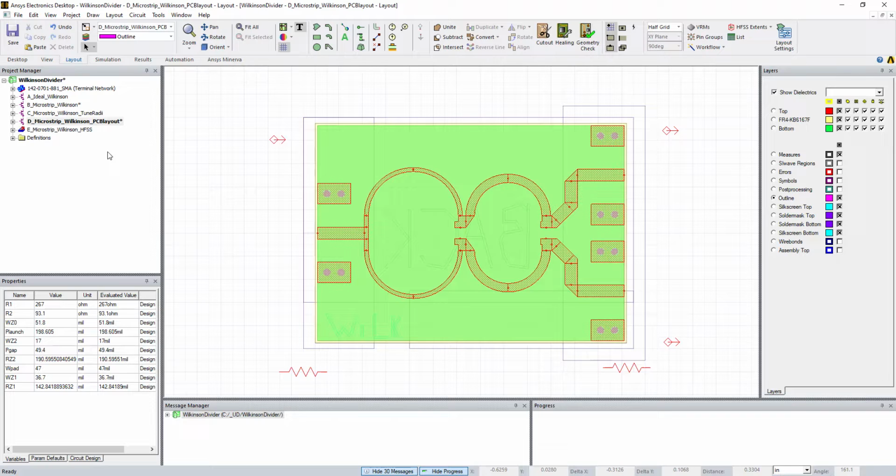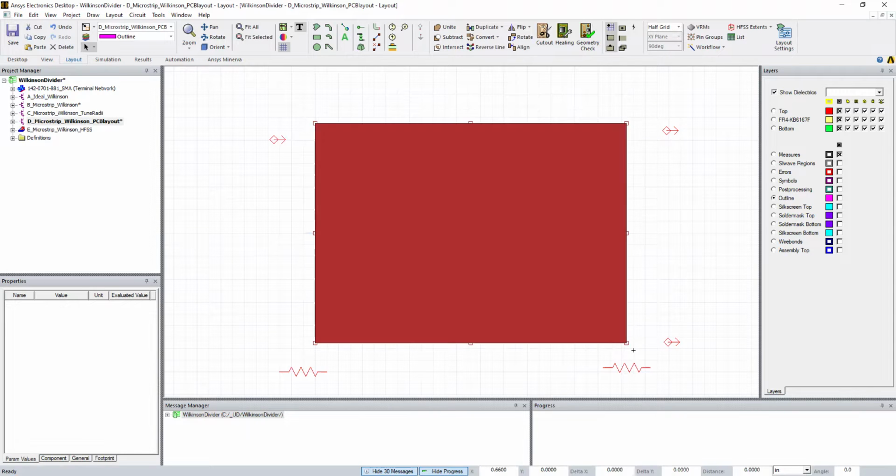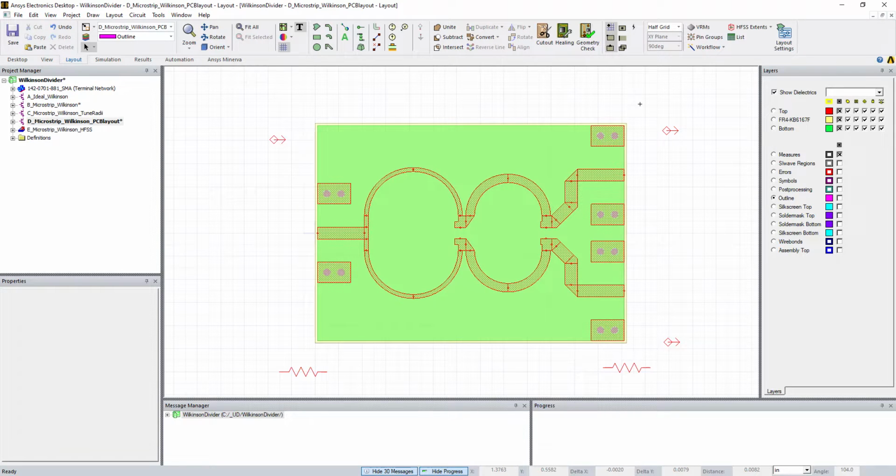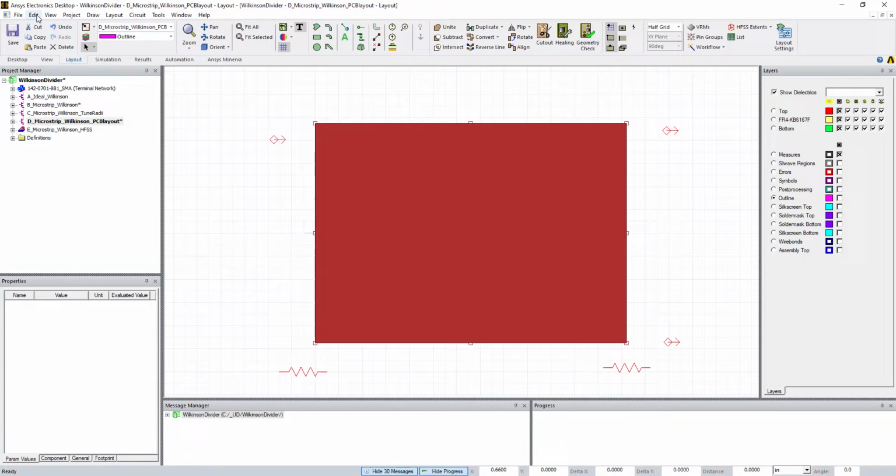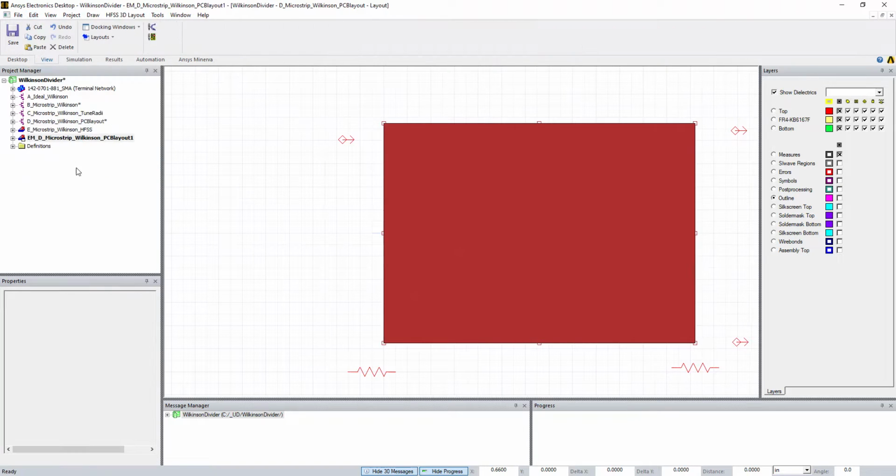Of course, then when you're all done, to look at this from HFSS 3D layout, what we're going to do is turn these guys off. We don't need these in HFSS 3D layout, right? We're only going to need these 3 layers. So to generate this one, I'll go through it real quick. We're going to highlight the board. Again, we just have the 3 layers here. Okay, we're going to highlight the board, and we're going to say edit, copy into HFSS 3D layout.